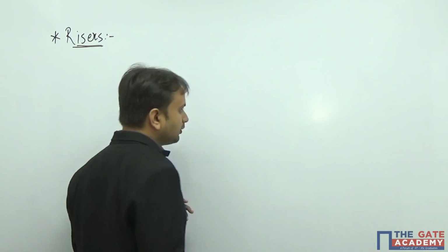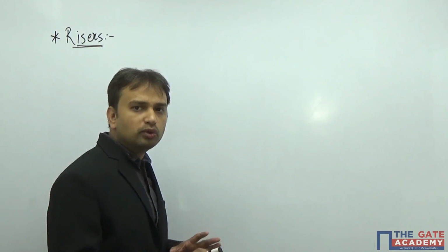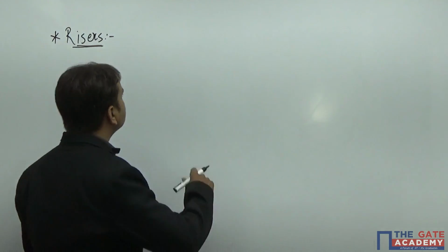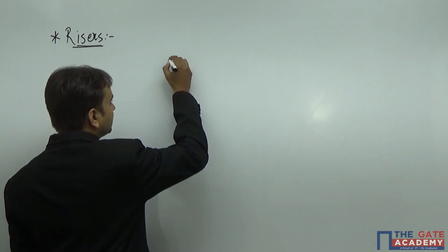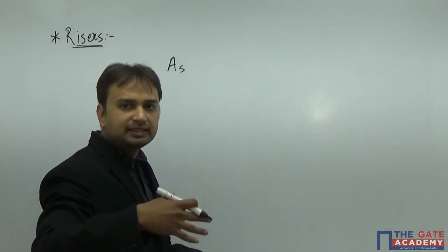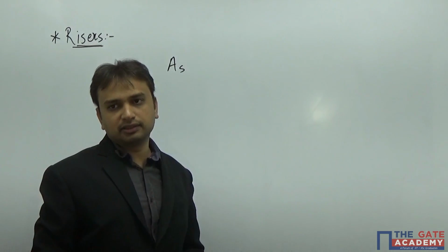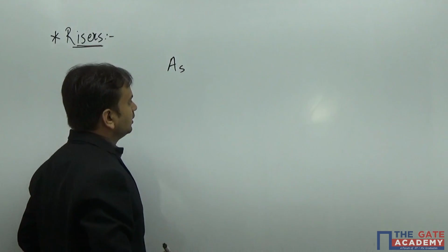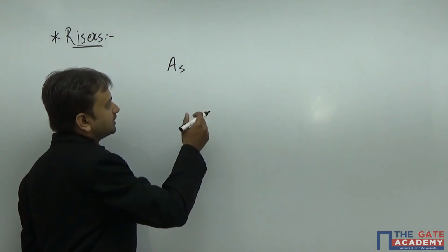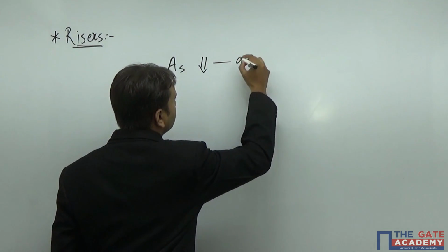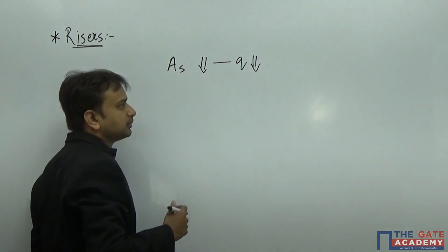What I can think of is that I have always observed that whenever I want to cool down something, I increase the surface area of that particular component, so that it can easily conduct or convect its heat, and it becomes cooler. Fine. So by decreasing the surface area, we can reduce the heat transfer from the riser.